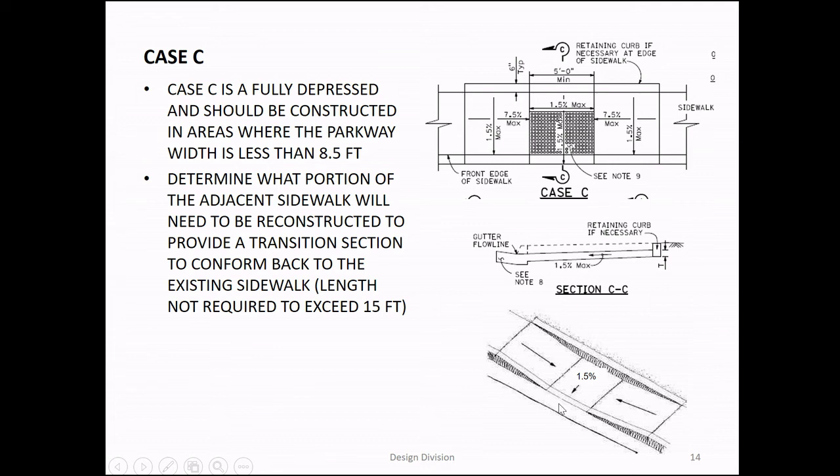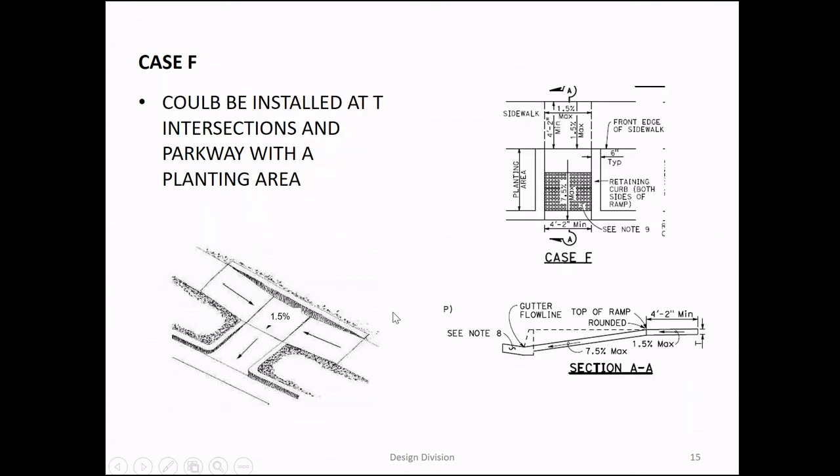No, ADA is 36. But don't forget that I mentioned that ProWalk is best practice, so 4 should be the minimum. 36 is the ADA minimum, and it actually allows you 32 on a very short segment, like 2 feet long. But, yeah, we should not get to that.